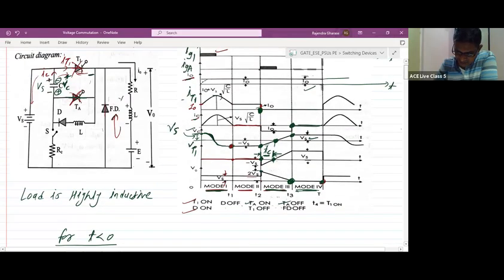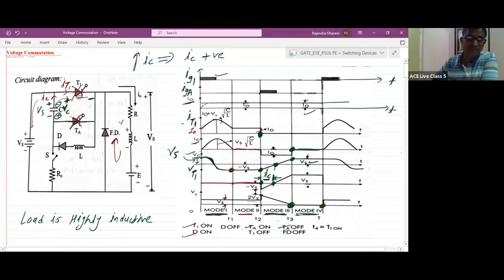There is no thumb rule like there should be 4 modes. In order to understand it, we have divided the circuit operation into steps. First, thyristor T1 turns on, then the capacitor discharges and again charges to the reverse polarity. Next, in mode 2, we have not applied the gate signal to the auxiliary thyristor yet. Then what will happen? Like this, we have divided the circuit operation.